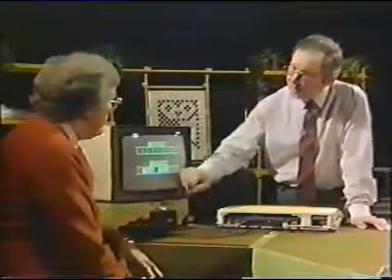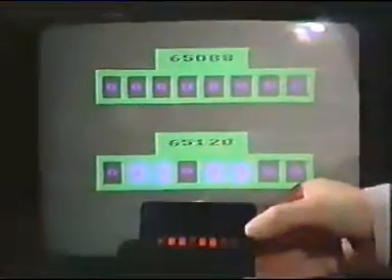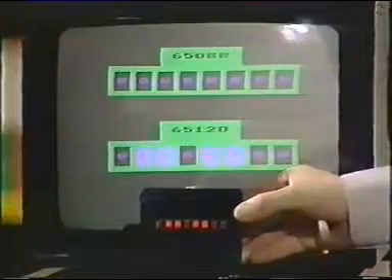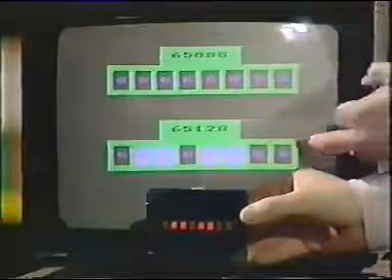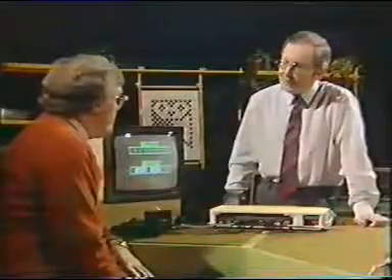These lights are connected to address 65,120. And you can in fact see that there's a mapping, or a relationship, between the zeros and ones here and the lights here. These two addresses here will be quite different on other machines, but I suppose they have a similar sort of thing. Well, yes, you must have on any computer system some way of getting digital information in and some way of getting it out. But as you say, there will be actual different addresses in different machines.